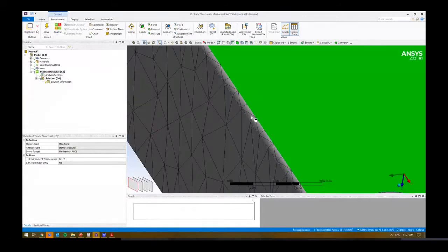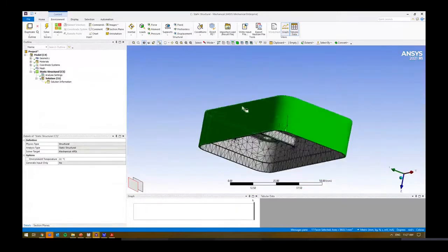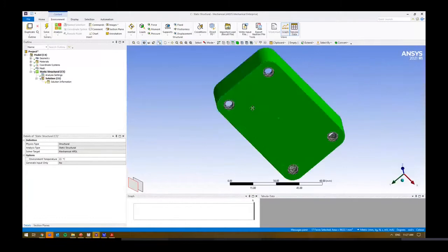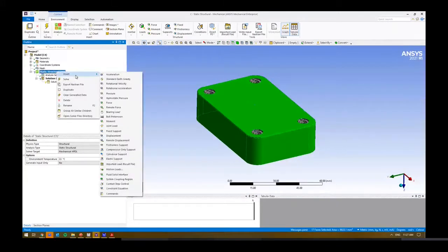Because we've got some radiuses around there, if I double click on that, it will extend it to the limits, right? So we see it extends it up until you get a 90-degree impasse. So we can do that, and I can right click on static structural. You'll notice the top are all my inertial loads. We've got my forces, we've got my supports, and then at the bottom we've got some additional things as well, right? We've got interfaces, contact sizings, and things like that.